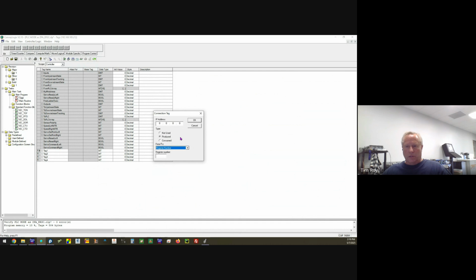So that's what these are used for. The good thing is we are not Allen Bradley. In Allen Bradley, if one processor is a producer, you have to configure the other one to be a consumer, and vice versa. You don't have to do that with our product. I could tell this module to produce and consume to 4 other modules because I have 4 tags, and those other modules would just accept the data or give up the data without any further programming required.